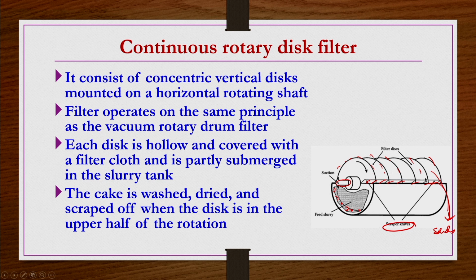So that the surface of the filter medium covering the hollow disc is free from the solids. It is not possible to have it completely free, but more surface is definitely available for filtration to occur in the subsequent rotations, because we are partially removing the solids, and this removal of the solids is continuous.